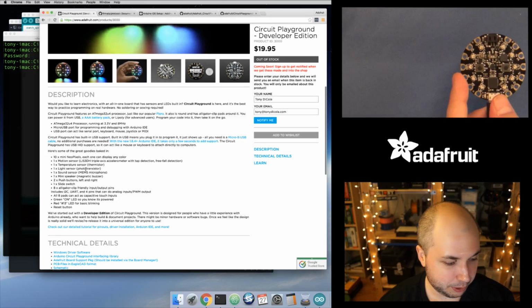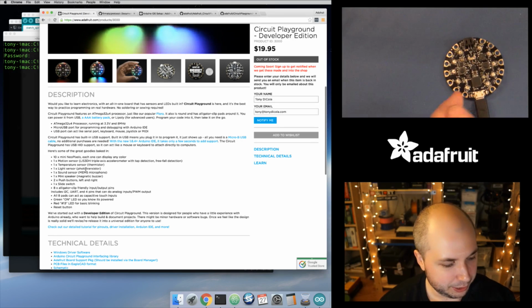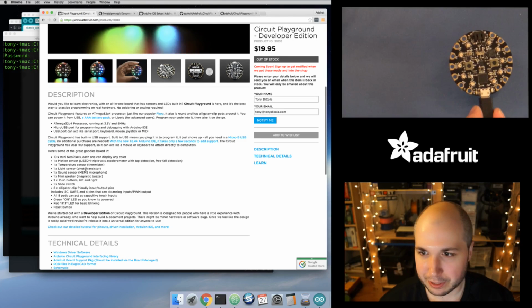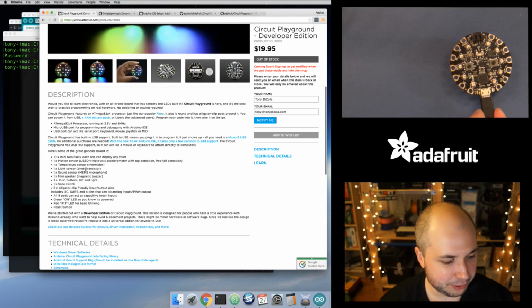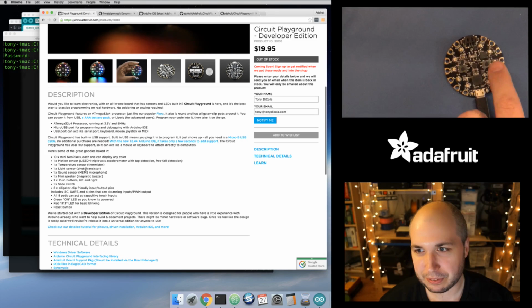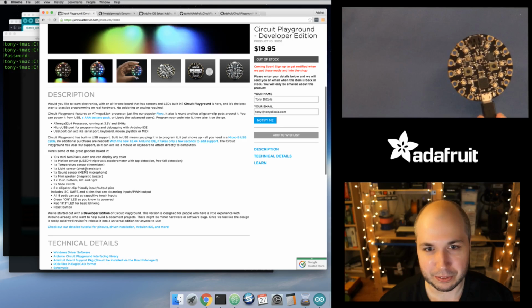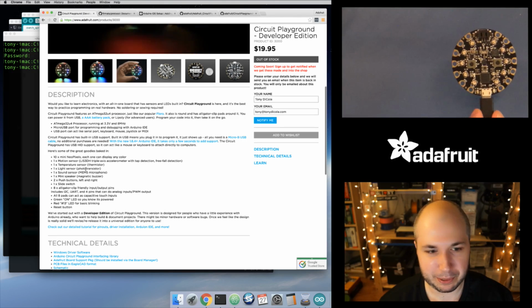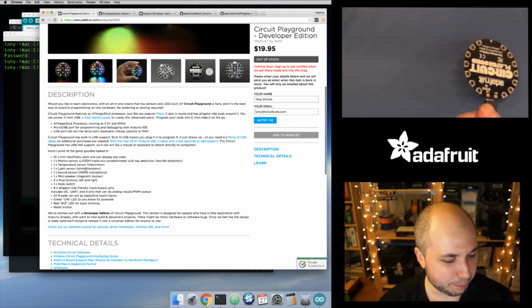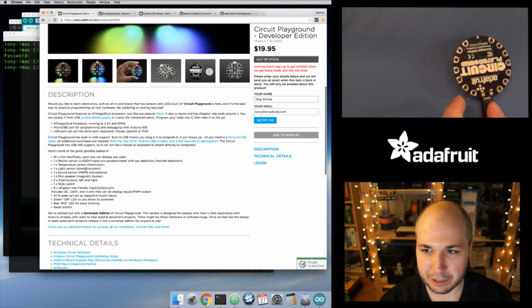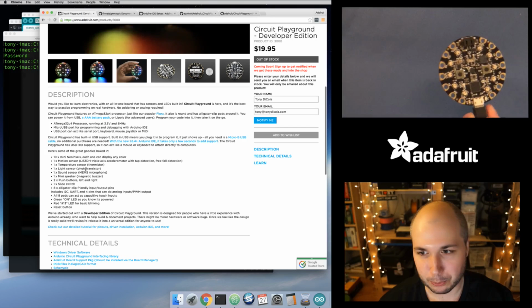They're also good if you want to make this a wearable project, so you could wrap some conductive thread around these and maybe tack it down with some solder, and you've got a cool thing to put on like a jacket or a shirt. And the neat thing is, because you've got the NeoPixels on board and even some sensors, just this alone is a cool little wearable thing. You can imagine putting it on a jacket. I was thinking a fun thing would be to just hot glue a magnet on here, to hold a name tag on a jacket, and then you've got a board ready to go.